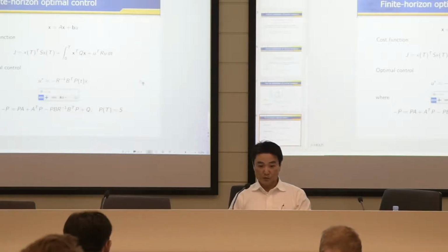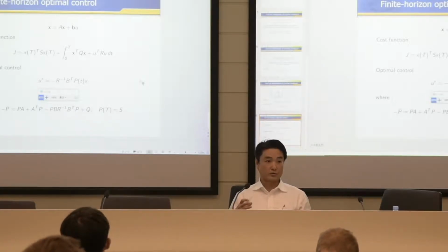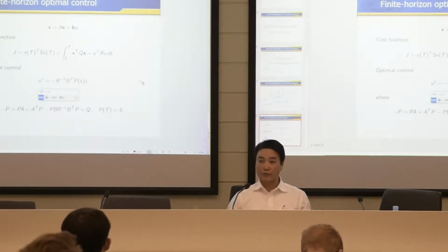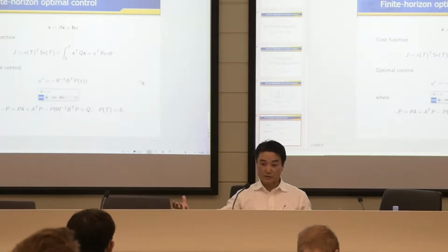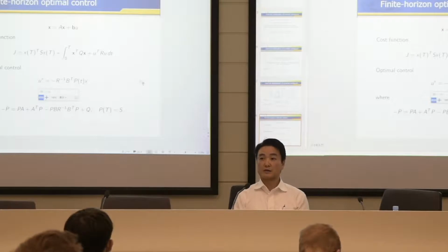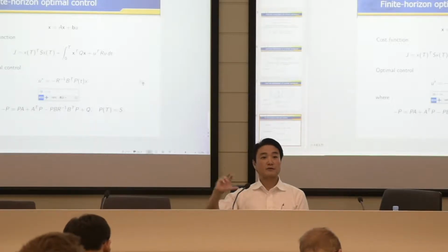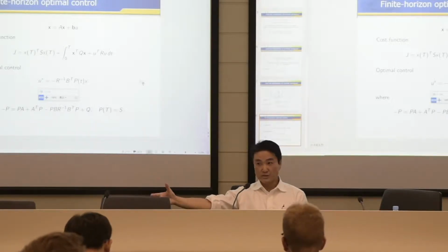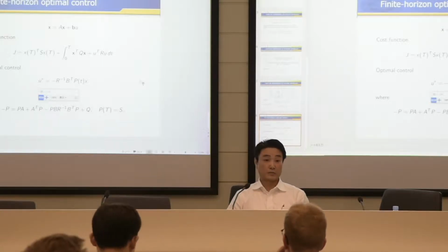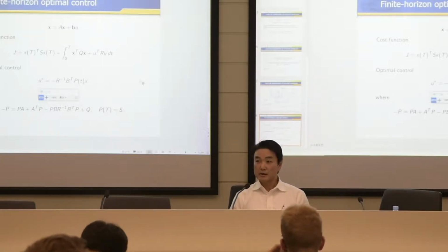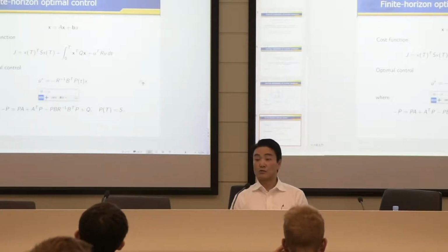But the important thing is to try to do the nonlinear or a full order simulation. Because using just a control model is not very surprising. Of course, it will be successful because you compute it based on that A, B model. But plugging into your own system, which may be nonlinear or which could be infinite dimensional, then you never know how your system behaves with this LQ control.